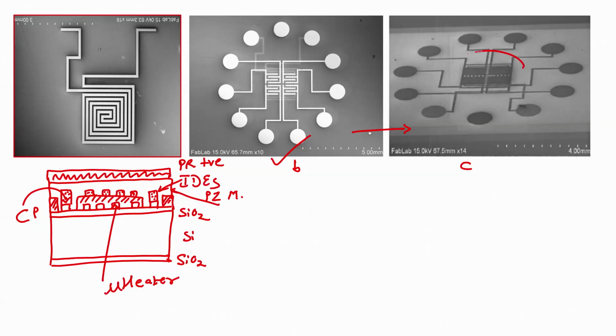I want to create this particular chip, you see here, right. The next step is, as we all know, we have to soft bake it. Soft baking can be done at 90 degrees for 1 minute on a hot plate.